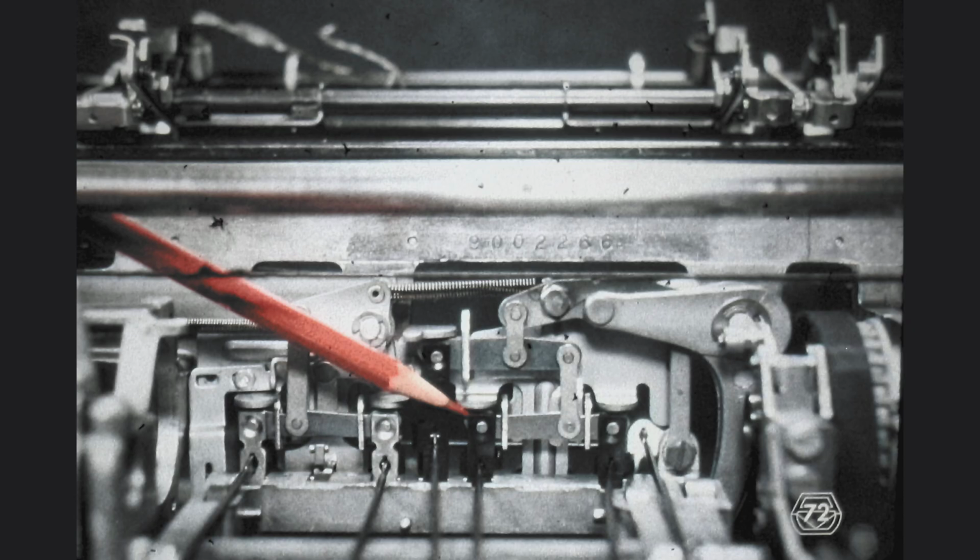Before we move on with our description of the mechanism, notice that the rotate differential has 3 horizontal levers. The lowest one is indicated by the red pencil. It is unbalanced because it is divided into 3 sections, just as in the case of the tilt differential. Immediately above this horizontal lever, we have another differential lever, which is divided into fifths. The link which transmits the motion upwards is located at 2/5 of the length of the lever from the right extreme of the lever and at 3/5 of its length from the left extreme.